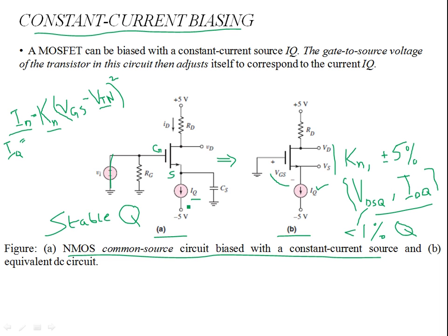That's the idea. And then again, you don't need a constant current source. Well, that's how it is depicted in the circuit diagrams. This is also accomplished by what you call a mirror NMOS circuit configuration. This is also based on an NMOS MOSFET. It's not a constant current source. It's again an NMOS circuit, just like you have enhancement load devices. A transistor can model a nonlinear load device. Even this load is also a MOS load, or let's call it an enhancement MOSFET device.